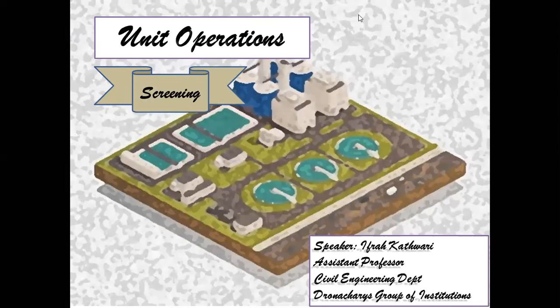So yes, in unit operations, the first one is the screening part, which involves physical force, wherein we remove the coarser particles, the coarser solids, from water. In screening, these coarser particles are removed with the help of screens, wherein we go for the surface straining of water. So as you can see, physical forces are used to remove the coarser solids from water.